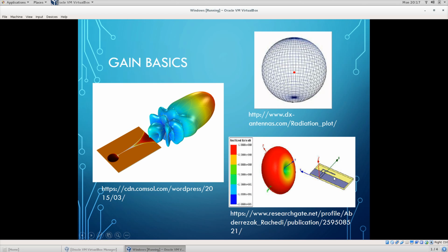Right, and you can kind of figure out why this antenna might look like that, because this right here that you're seeing, this is actually the antenna, and it looks kind of like an inverted F type antenna. This antenna is very popular for cell phones because it can be made planar. This is the ground plane for that antenna. This is the actual radiating element, and it can be made very small, and you can make it fairly omnidirectional, which is what you want for a cell phone, since a cell phone can be moving all over the place and seeing lots of other towers. Right, so you want an omnidirectional antenna.